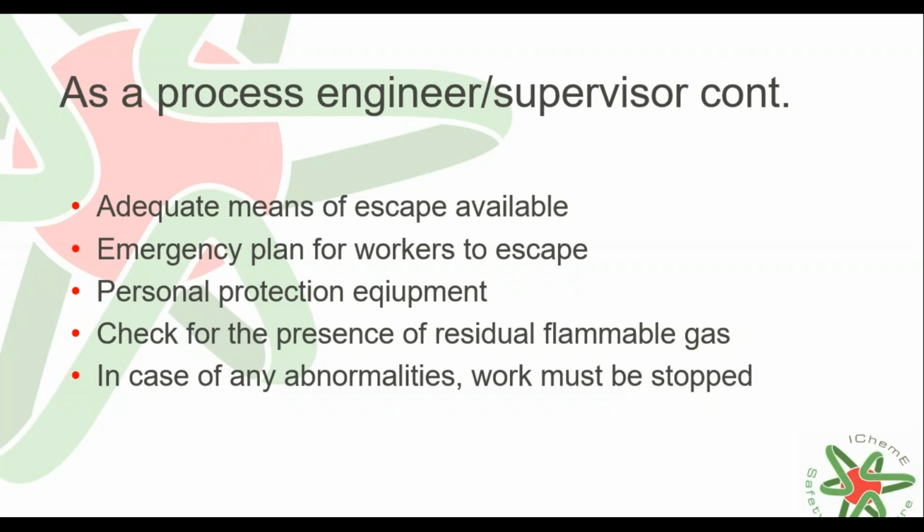Prepare an emergency response plan to enable workers to escape or act upon in case of emergency. This seems trivial, but it's again coming from different cases. So it is a bad practice that sometimes there is no emergency plan prepared. Check that all personal protection equipment that is required for the work is present and fit for purpose. Workers should wear fireproof suits until the lines are proved safe. Check for the presence of residual flammable gas, avoiding a flammable atmosphere.